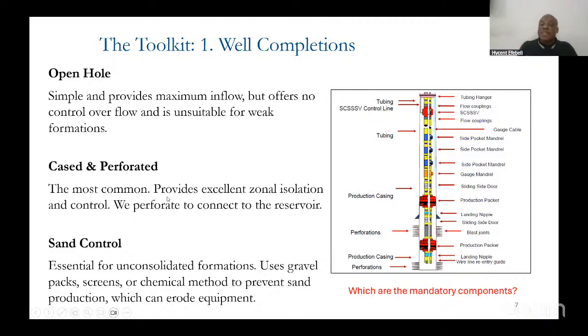You don't need them in every well. What you choose to complete a particular well depends on the functionalities you're expecting from that well, and also the thought of future well intervention, then economics. You are looking at all those as you are completing your well. You can see the packer actually helps us isolate zones.